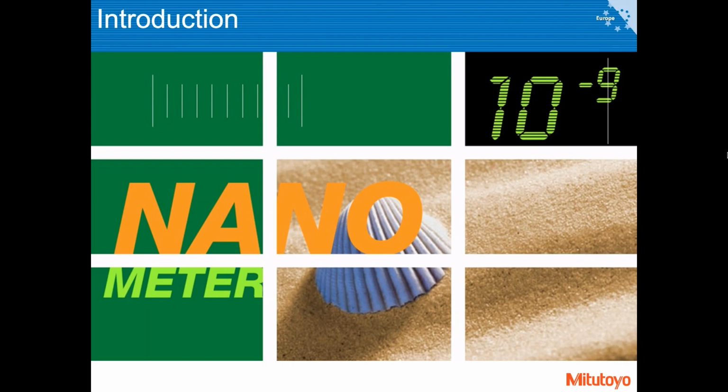So you have the main cylinder, let's say, and you have a cap on this cylinder, and you need to seal it somehow. One way is to prepare those surfaces very smooth, very parallel, and then you can physically compress them together with bolts. But an easier way out typically is to use some elastic material in between.